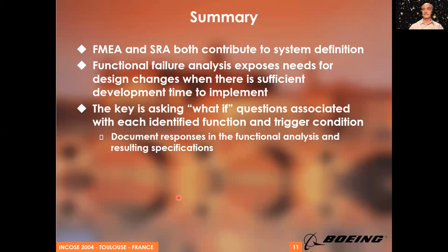So in summary, both of these activities contribute to the system definition. If we can perform the failure modes and effects analysis concurrently with the system requirements analysis, then we're going to have less rework. But we have to be asking the questions about, well, what if certain failures are experienced?